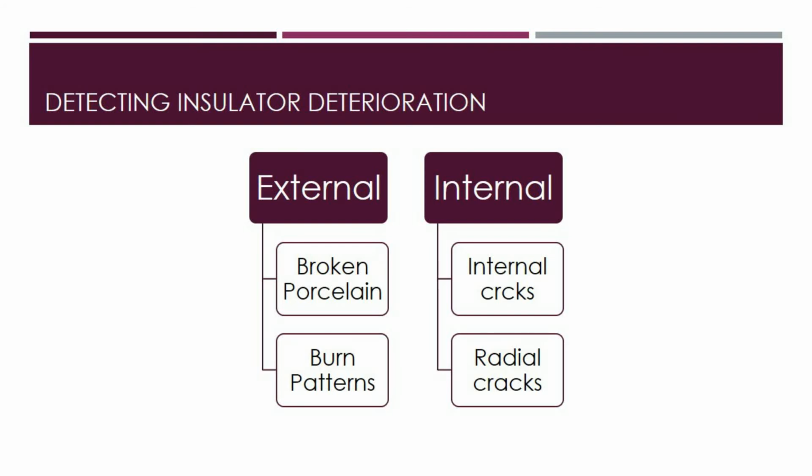Moisture getting into the glass fiber rod region is a common cause of failure. Cuts, splits, holes, erosion, tracking, or burning of the rubber shed and sheath material, as well as separation or degradation of the rubber sheath material where it meets the metal end fittings, are all visible damage to the insulator. Any evidence of a power arc, lightning damage, or corrosion on the metal and fittings indicates that the component is deteriorating.